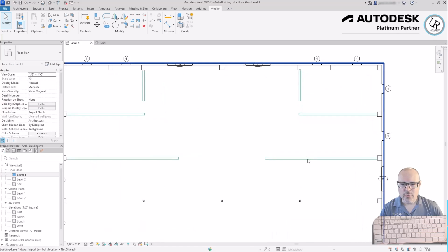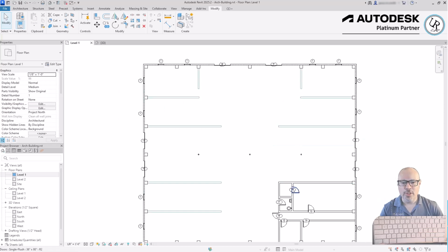You can, however, use the AutoCAD file as a background or an underlay if you just want to see that two-dimensional content as a reference, but you're not going to show it in 3D or other areas. It can be used as just a reference of a portion of the building if you're not responsible for drafting the whole building. If you're not getting paid for modeling the whole building, you don't typically have to, unless it's stated in the contract.